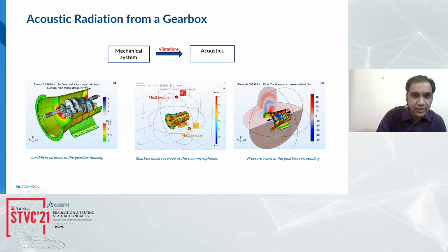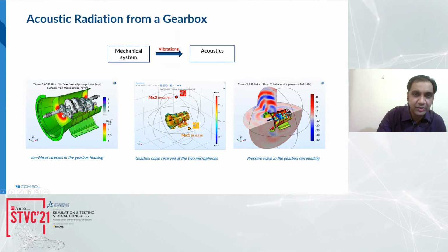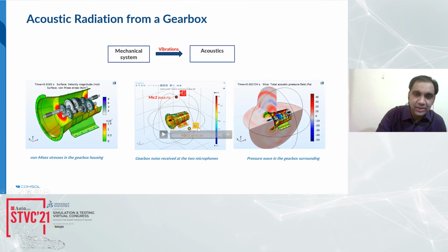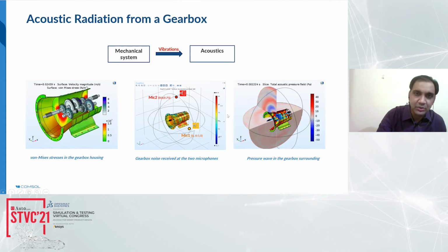For that purpose, you can model the surrounding domain and find the sound pressure level on the housing as well as in the exterior domain. It is also possible to place microphones at different locations, and you can also listen to the noise coming from different directions and at different distances. In a similar manner, a motor noise analysis can also be performed.